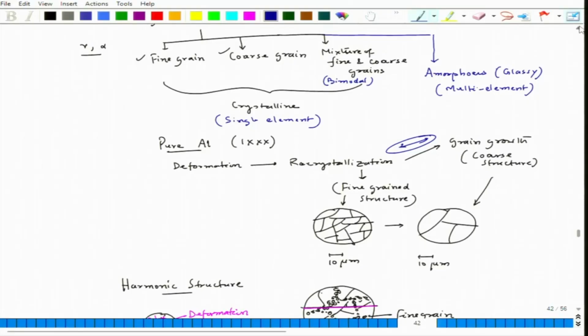Fine. So, that means grain boundary is the weak point when we compare the corrosion behavior. Then the obvious thing is that if you have a coarse structure, it will have less attack, and gradually we should have higher corrosion resistance compared to the fine grain, because in the fine grain you have a lot of grain boundaries, so it should attack more.